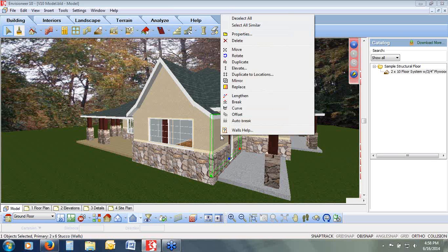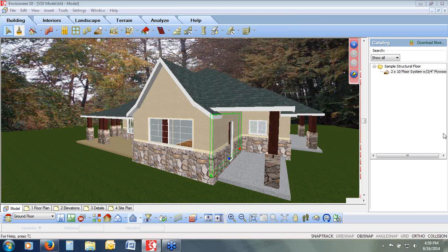And one of the features of our walls is you can have it automatically break. So if you have your panels at a set size, that can automatically break to those panels. Or you can break it at any point that you want to as well. So if you wanted to auto break every 5 feet, you can designate that, or just break it at certain spots. So yes, you can handle that.